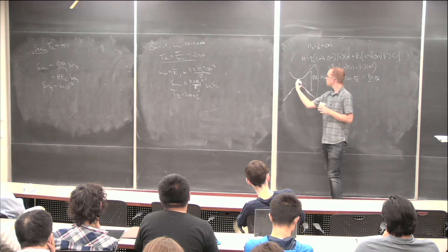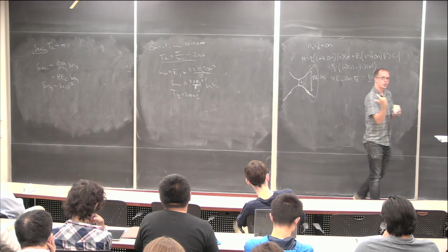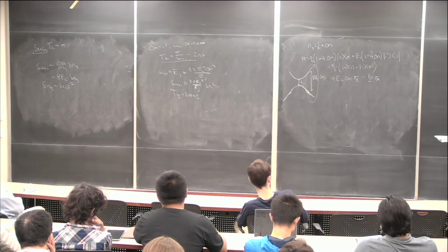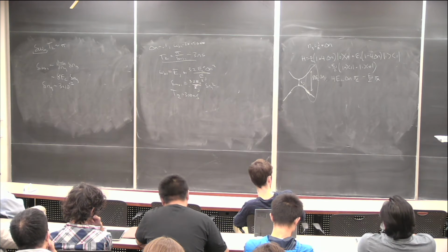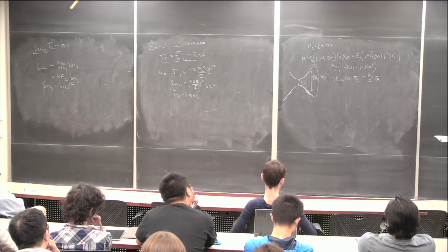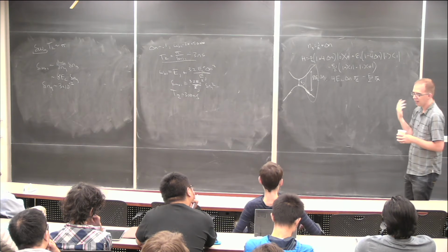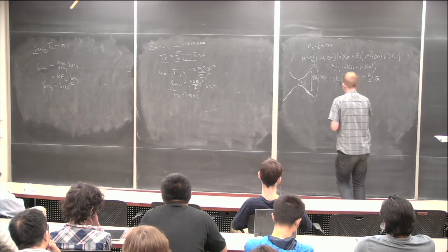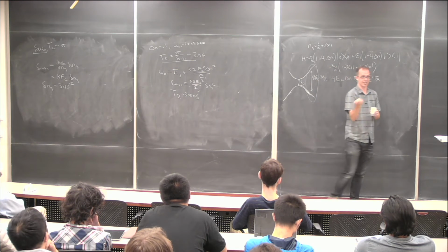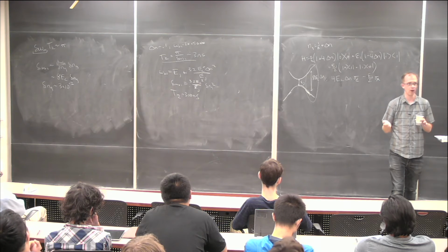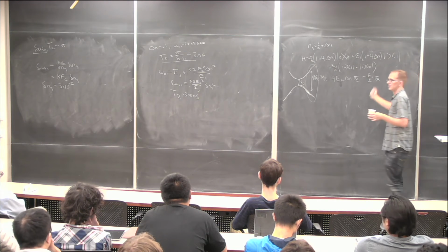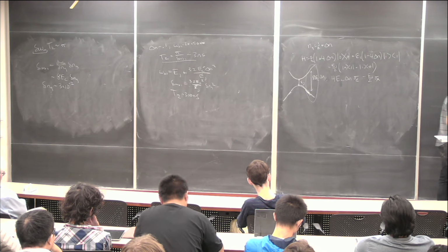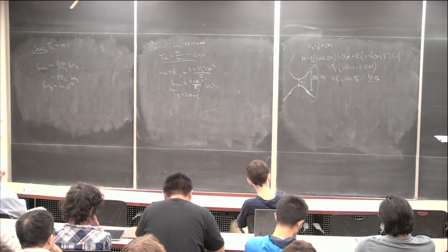So one, we've moved to a point where we are not sensitive to the gate voltage, which is great because the gate voltage was a lousy knob. There was a lot of schmutz on the chip that was twiddling our gate voltage and causing decoherence. But we now don't have a knob, and so if we don't build a device where EJ is exactly the frequency of our qubit that we want, well, we can't change it, right? Because we've intentionally said we're not going to use our gate voltage to tune that knob. So that's one problem.